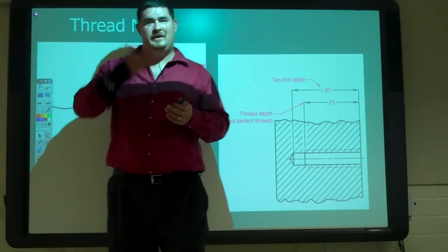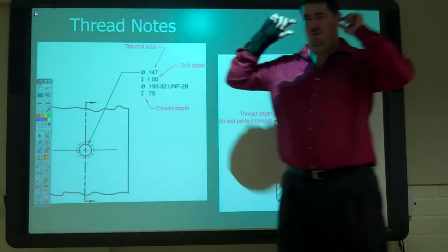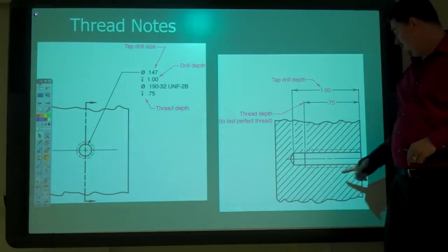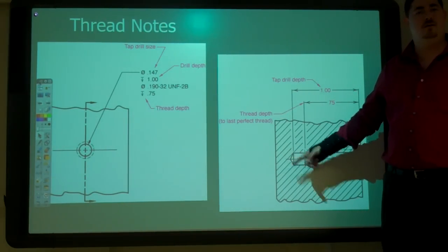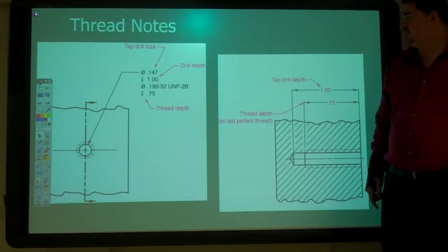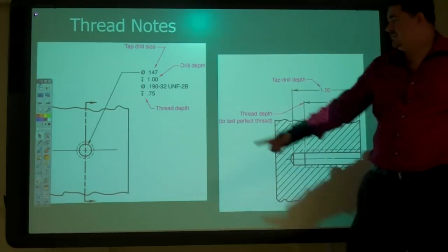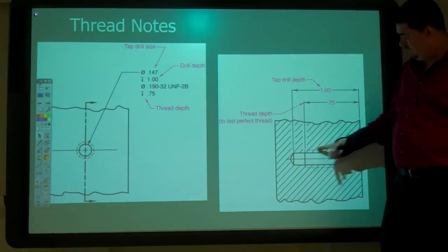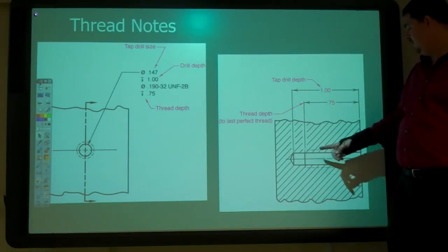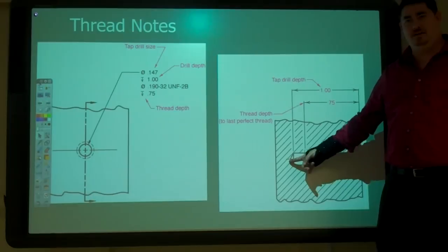And when we measure holes, we always measure to the flat, to where the wall of the hole goes. So here the 1 inch goes all the way down to there. Then the tip is on the end. The little line with the arrow, that's the surface depth, from the surface down, right? Yep. So from the surface here down. And then the tip is on the end.